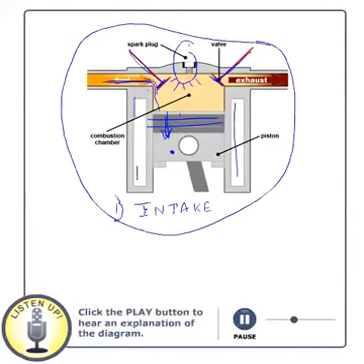And the second step is we close both of these valves and push this mixture. By pushing the piston up, the mixture in here is compressed to very high pressures, roughly about 8 to 9 times. And this piston moves back up here, and again we have to spend energy to move this piston up or compress this mixture.